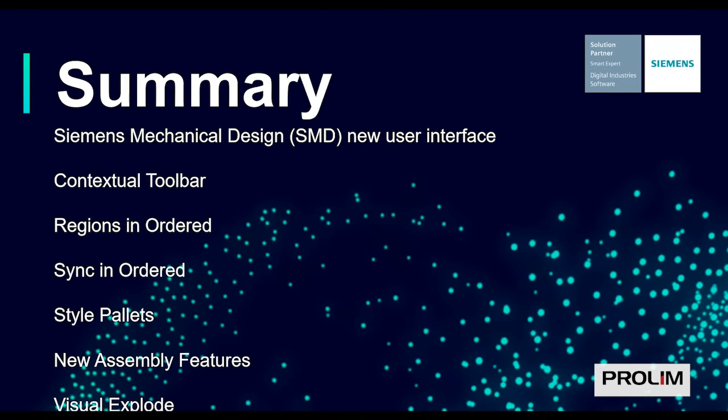We also learned how to quickly and easily add realistic rendered materials directly to the Solid Edge assembly environment by using the new Styles palette. Some of the new assembly features added this year, swept, cutout, subtract, union, and slot, with the capability to select multiple bodies to cut from, is a game changer. And then finally, we saw the very easy way to explode our assemblies using the new visual explode command. This again keeps us right in the assembly environment instead of having to jump into the ERA or the explode, render, animate environment to make these changes, ultimately saving us valuable time and effort getting those products out the door even quicker.